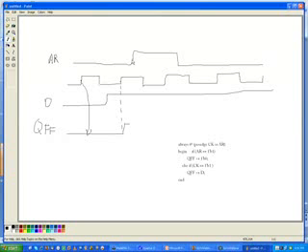Now, here the asynchronous reset comes along, it changes high. So we would come into this because it changes on either edge of the asynchronous reset. And we said if asynchronous reset is 1, which it is, then we force the output to low. So this is going to cause this to occur, right? Okay, so now our next event is going to be at the positive edge of this next clock.